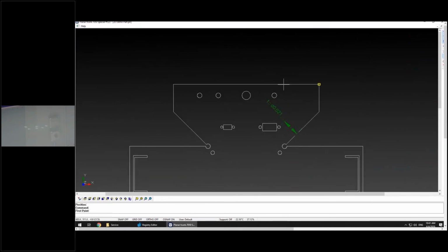if I do the opposite dimension, because sometimes it wants to snap over here, sometimes it wants to snap there. It can snap to the end of one of these boxes. So a way to make life easier, again, is to turn off the O snaps, knowing what you're going to measure, and then from there, your life's going to be a lot easier.